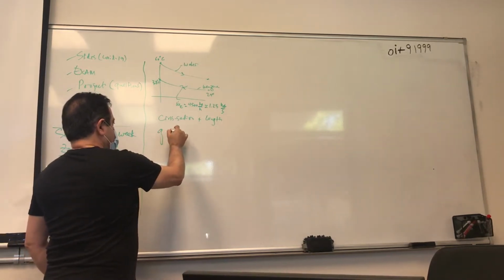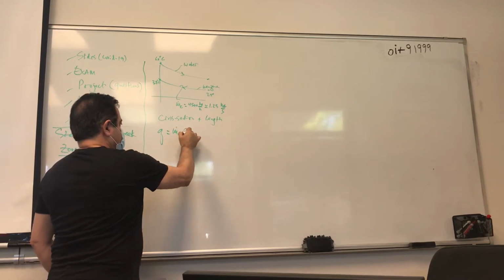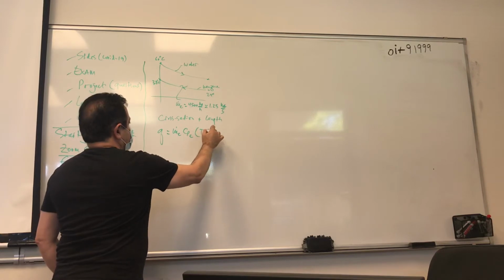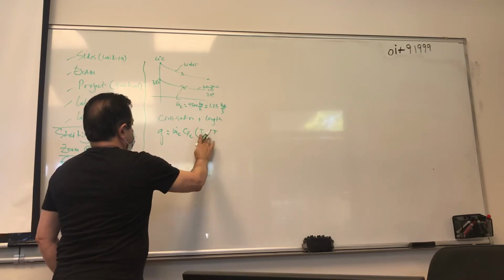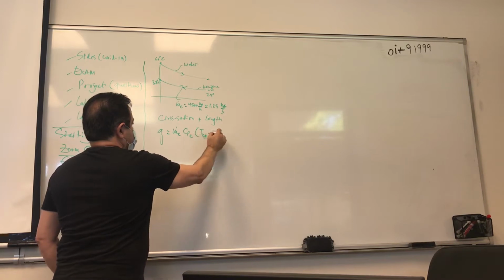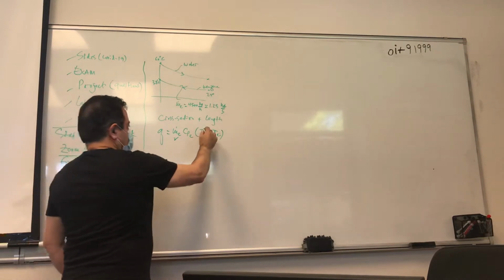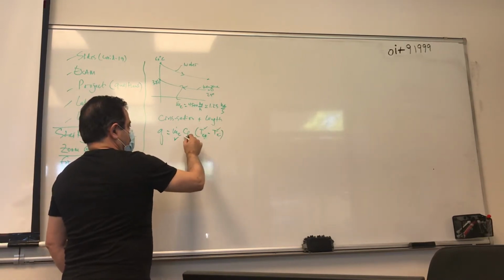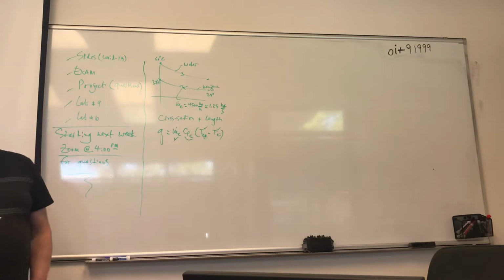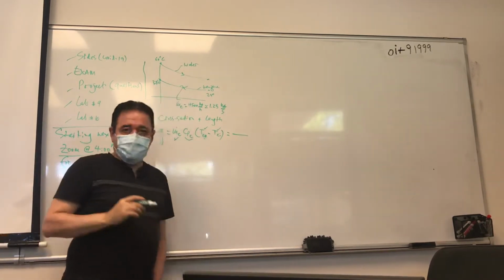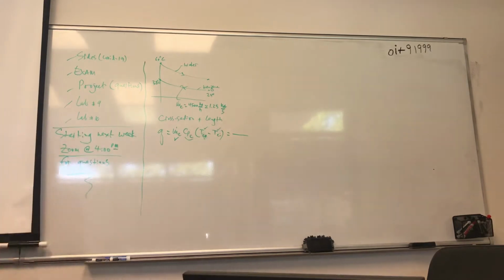Because Q is going to be equal to m dot C times Cp C times T cold out minus T cold in, right? This is known, this is known, this is known. How about this one? Yes, it is known. From the data that I gave you, you should be able to interpolate that value, okay? So you should be able to get a pretty hard value there for Q, right?